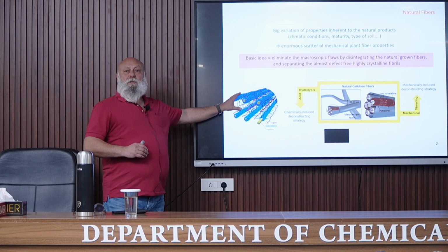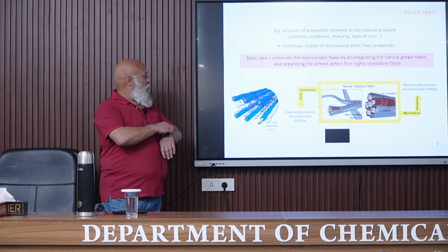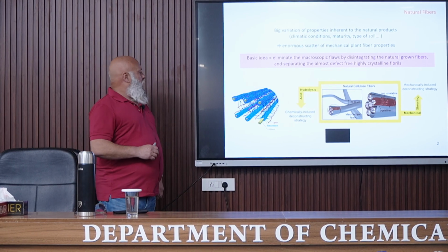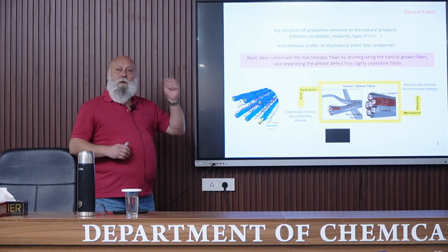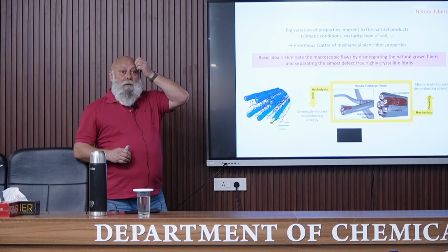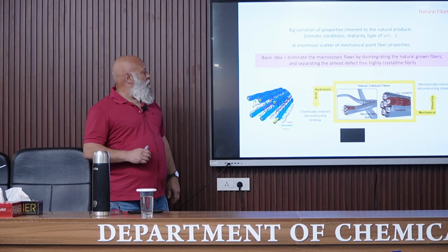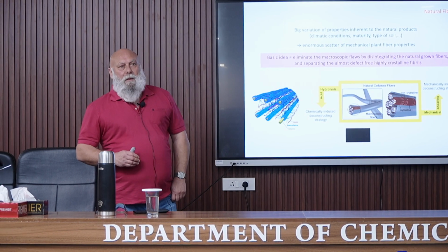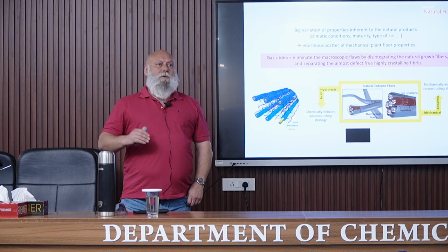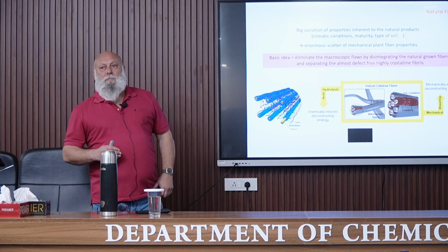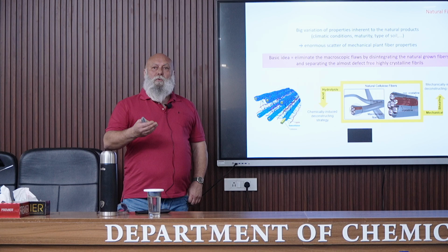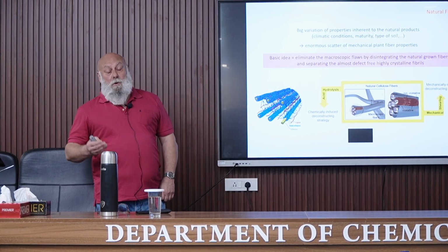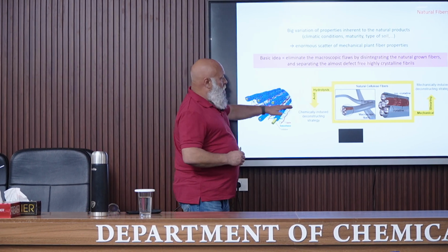So you remember the composition of natural fibers consists of cellulose, which is a structural element, and it is surrounded by a matrix composed of lignin, and hemicellulose acts as a compatibilizer between these two materials. Usually, purified natural fibers are used, so cellulose fibers are used, meaning that the first step to obtain nanoparticles consists in the removal of lignin and hemicellulose, and then these cellulose fibers have this structure.